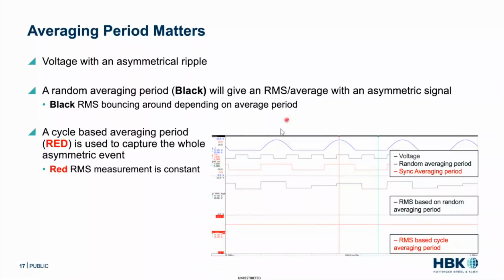And these are simulated signals, so this is really kind of the idealized world. But if you use the right period, you just get this totally flat RMS value. That's because we're not chopping off part of a sine wave here and getting a sine wave and a half there, or getting no sine wave in the middle. So this is a little bit of an extreme example.